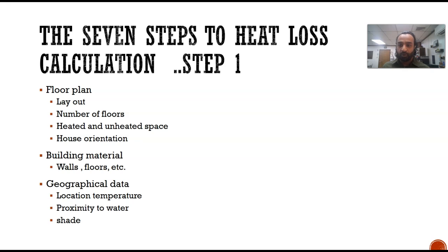It's very important also to know the number of occupants, how many people are going to be living there, because that will play a vital role when it comes to ventilation. And I cannot emphasize that more. You need to have the proper ventilation. A lot of people underestimate the heat because they do not account for ventilation for places with high occupants, and that becomes a safety hazard when the place is not getting the proper air exchange.